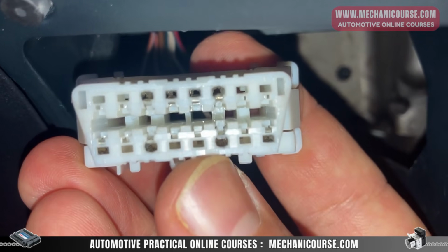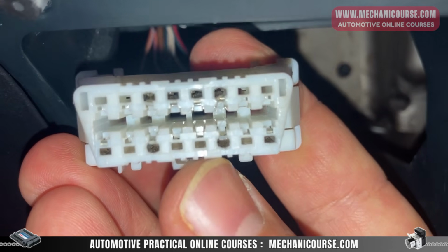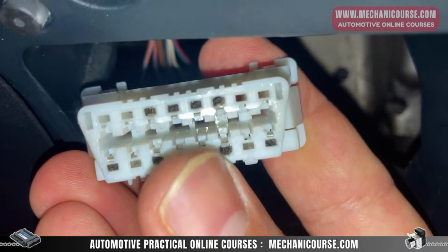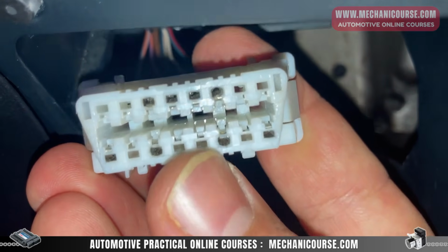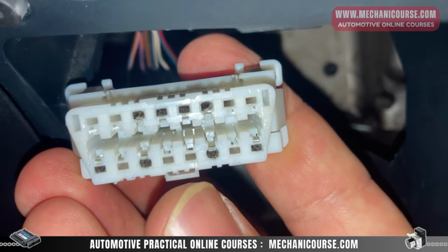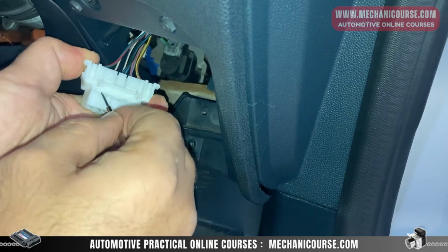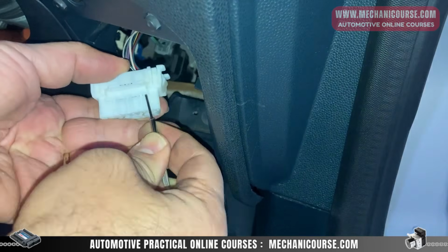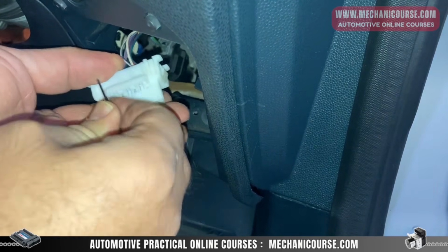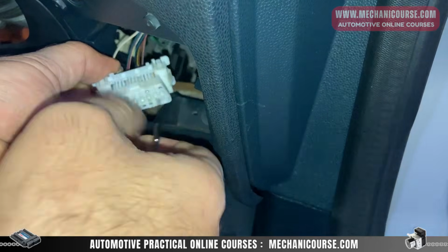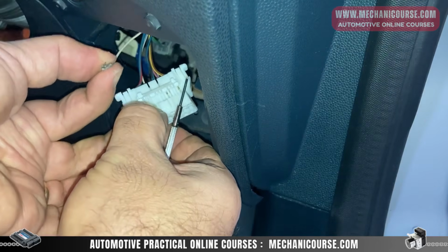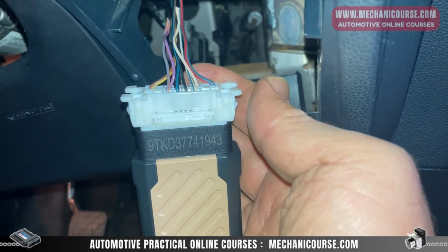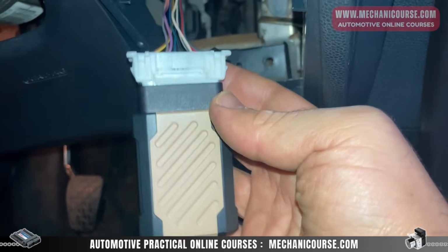So clearly this could be the no communication issue, because CAN bus is working right now, but the connection on the pins is not correct. So I'm going to go ahead and remove these pins from the OBD2 connector, fix them, put them back in the connector, and we will try it again. This one is widened a lot more. I fixed the pins, inserted the pins back into the OBD2 connector, and connected the VCI.